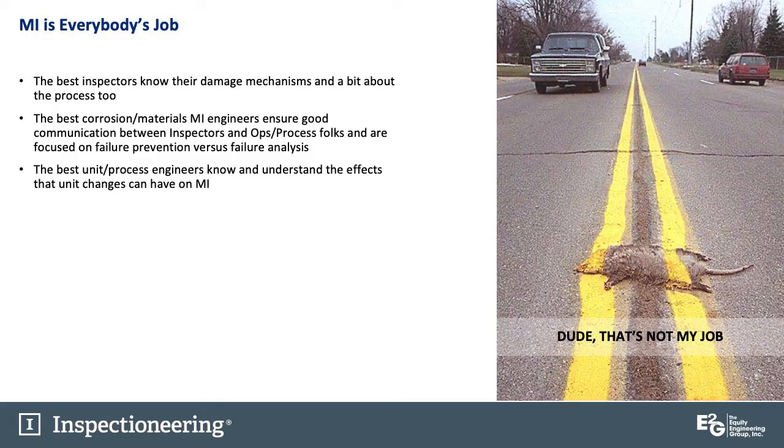And then the best unit process engineers know and understand the effects that unit changes can have on MI. They're not MI experts, they're not corrosion experts, they're not inspection experts, but they should have the basics to know that, okay, if I have a high ash content in the bottom of my FCC fractionator, that could mean erosion in the bottom of the fractionator, and I've got to make sure I'm talking to mechanical integrity people about that. So MI is everybody's job.